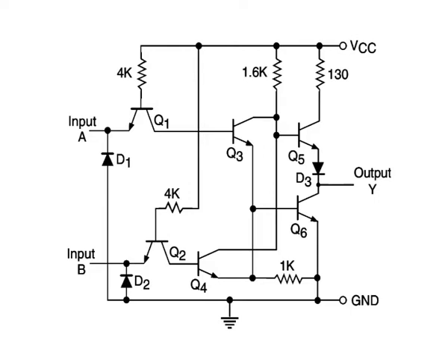On the input side, there are 2 separate transistors instead of the multi emitter transistor of the NAND gate. The inputs are fed to the emitters of the 2 transistors, the collectors of which again feed the bases of the 2 transistors with their collectors and emitter terminals tied together. The resistance values are the same as those used in the case of NAND gate. The output stage is also the same totem pole output stage.